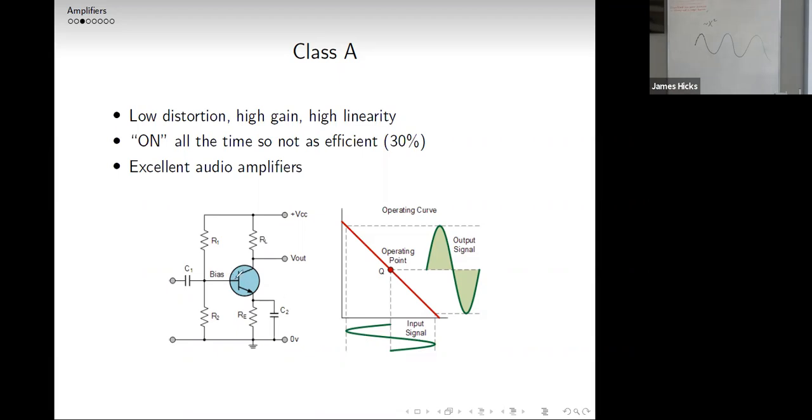If you look here at what's hooked up to the base, it's the regular voltage divider base biasing that we've done for all these transistor amplifiers. The benefit to that is that you can lift up the whole signal so that the entire signal is being amplified.